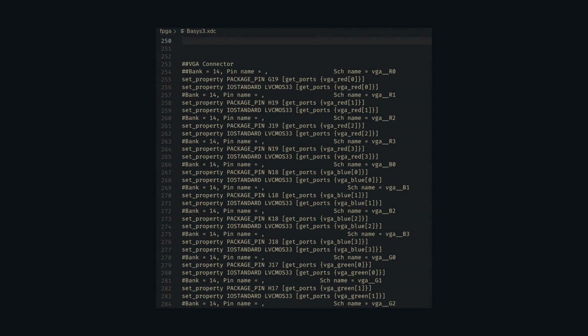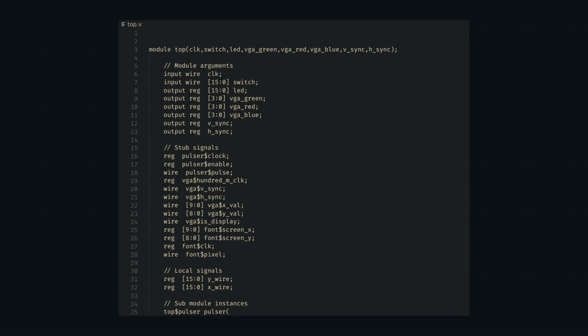We also need one more file which tells Vivado which signals in our design are going to connect to which pins on the actual chip. You'll usually get this from the person you bought the board from, and you just uncomment which pins you're using. Secretly, you can uncomment all of these and it still works, just Vivado will give you critical warnings about undriven nets, but who cares? I changed my signal names over to match what I'll use in Rust. Now I need a top.v file which will contain my design.